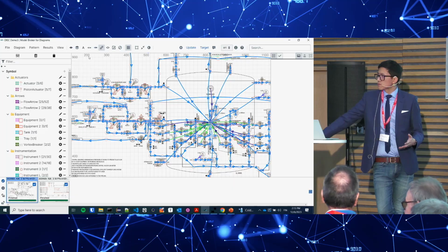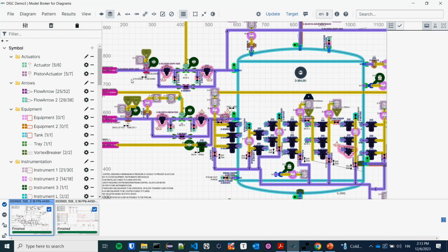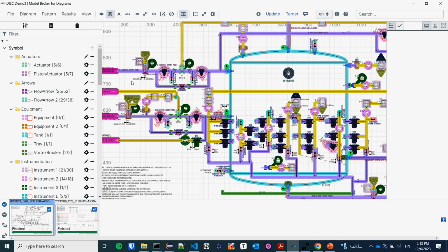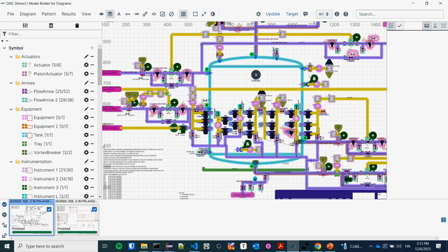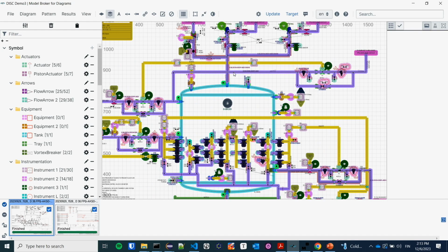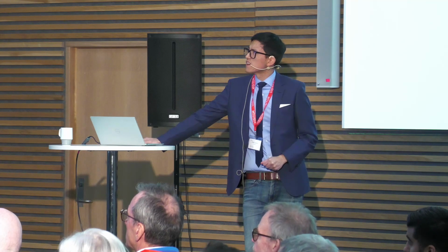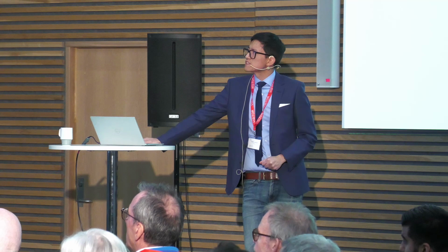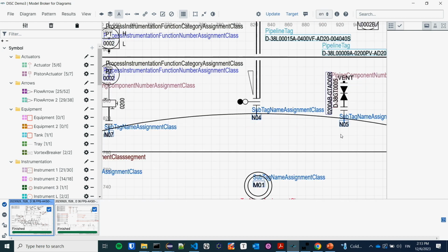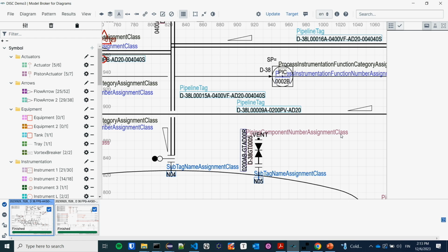But then of course, most of us would want to have the XP file where connectivity information is also available. So here you can see Hanu is showing all the different symbols that are found after recognizing this diagram. Hanu, can you show now the attributes as the text there? It's a bit messy, but if we zoom, you can see how, for example, the text that we are finding is then mapped as some of the attributes of the specific element that we're finding. And then Hanu, if you show the connectivity, you were already showing it, but there it is.